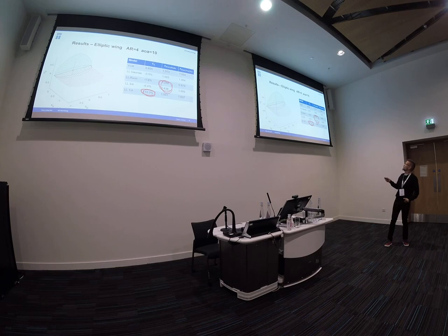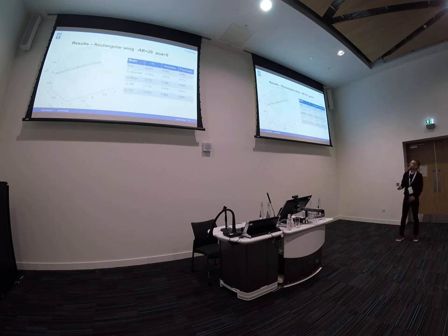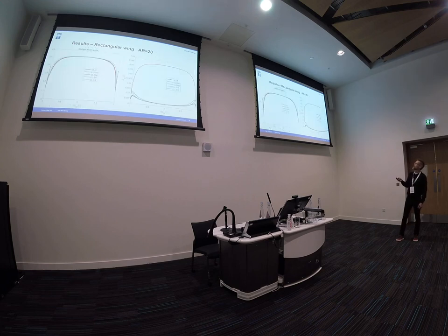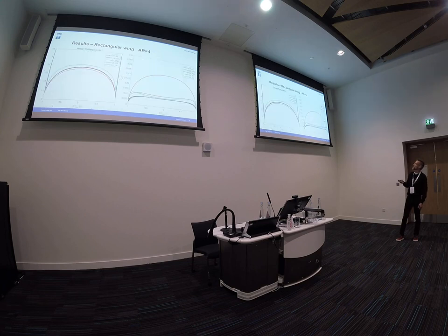These 2 methods where you evaluate at the 3/4 chord velocity and regard that velocity as the reference direction that you put the forces on, you get the drag completely wrong. And again, VLM truth is black. The thing I claim to be a good idea is blue, and it looks good. Rectangular wing, more or less the same conclusion. High aspect ratio. Blue and black look really good. Low aspect ratio, same story.